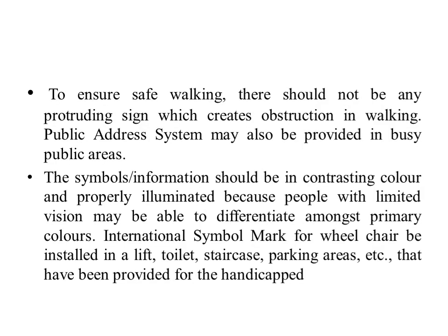Then to ensure safe walking, there should not be any protruding sign which creates obstruction in walking. Public address system may also be provided in busy public areas. The symbol or information should be in contrasting color and properly illuminated because people with limited vision may be able to differentiate amongst primary colors.